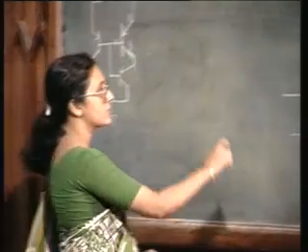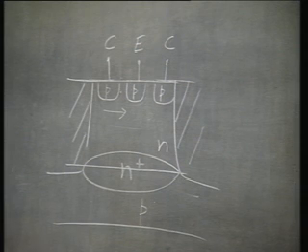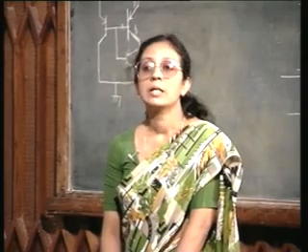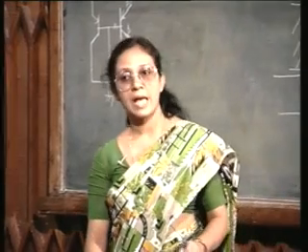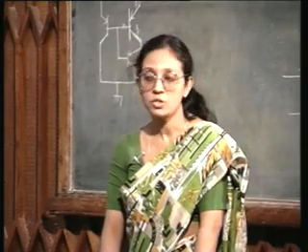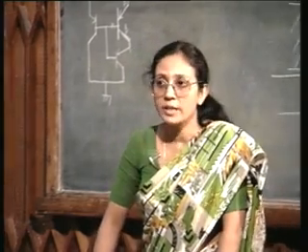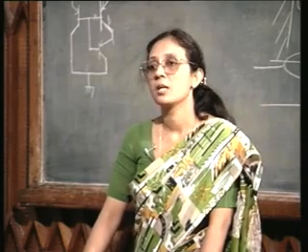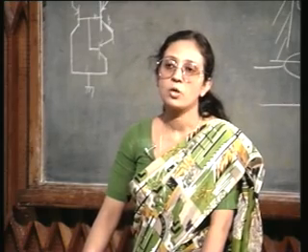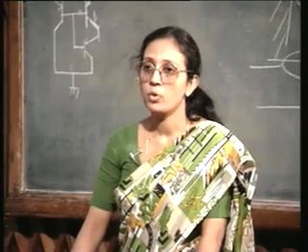However, if you look at this parasitic PNP transistor, its gain is very low because of the N plus buried layer. Because of the presence of the N plus buried layer, which is the base of this PNP transistor, the gain of these parasitic transistors is going to be very small, and therefore, it is not going to affect your actual PNP transistor performance to a large extent. So, this lateral PNP transistor is a feasible design, and in fact in almost all integrated circuit bipolar junction transistor designs, the PNP transistor is always a lateral transistor, while the NPN transistor is a vertical transistor, because you want to incorporate a PNP transistor in the same process flow as the NPN transistor, and this can only be done, as you have just seen, if we use a lateral design.